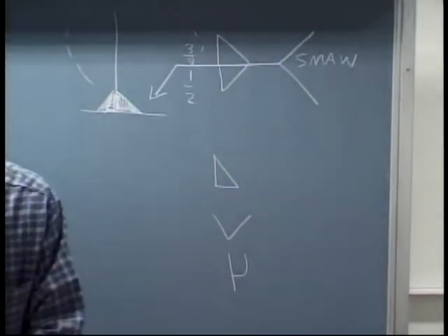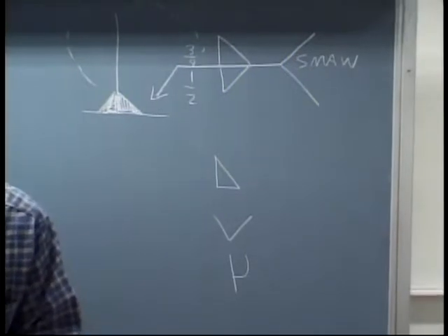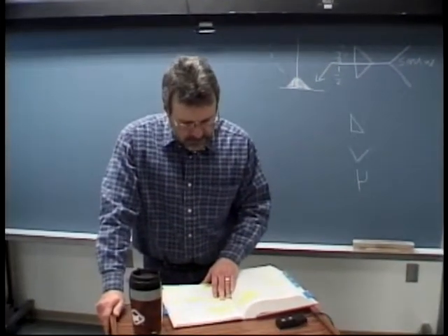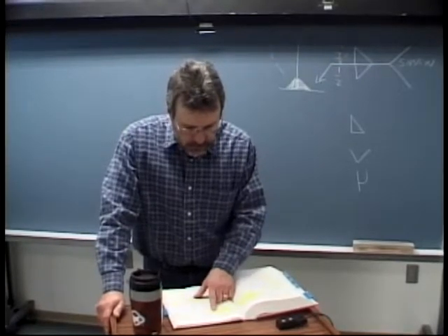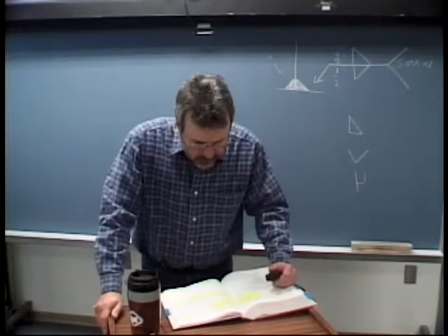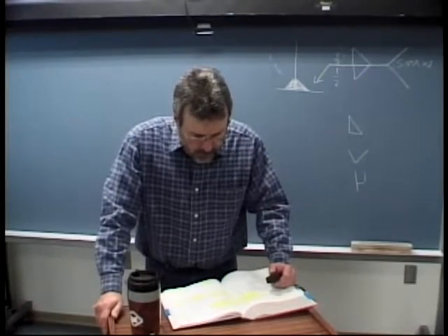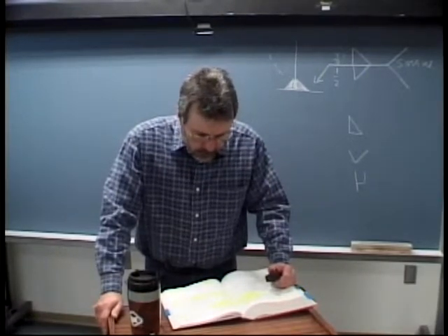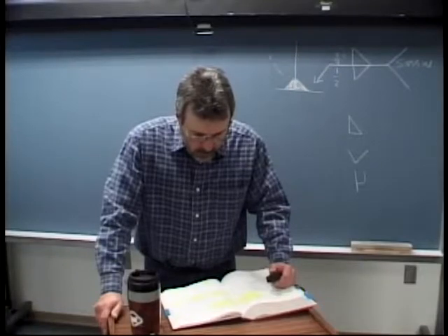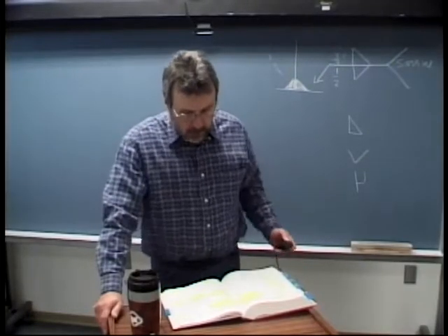Okay, so reading from your text, the AWS standard makes a distinction between the terms weld symbol and welding symbol. The weld symbol, figures 30-3 and 30-4, is the graphic symbol that indicates the weld required for the job. The assembled welding symbol, 30-5, consists of the following 8 elements, or as many of these elements as are necessary. However, only the reference line and arrow are required.